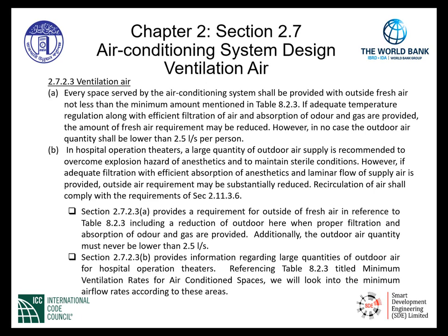And it gives a very specific table. Table 8.2.3 is referenced. We will take a look at Table 8.2.3 and work through a calculated example for ventilation, mechanical ventilation. As seen here, the minimum airflow quantity cannot be lower than 2.5 liters per second per person.